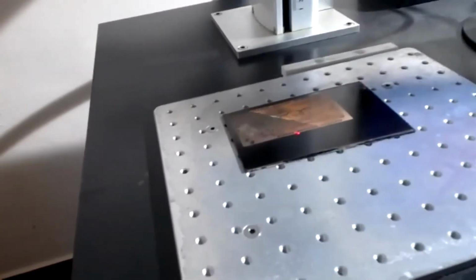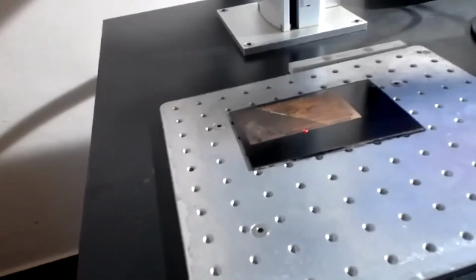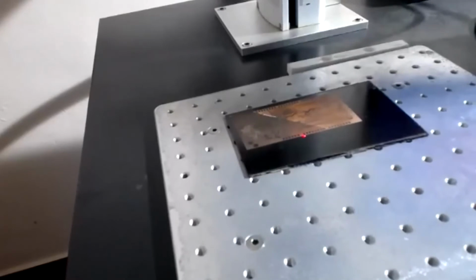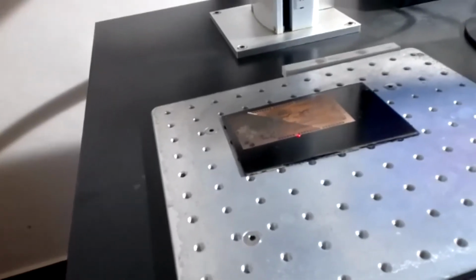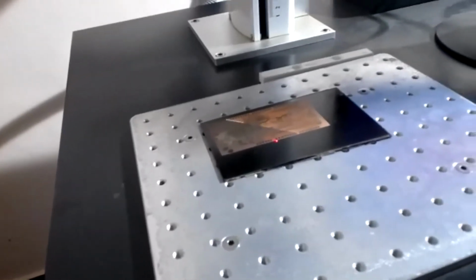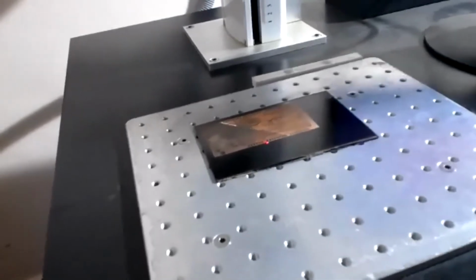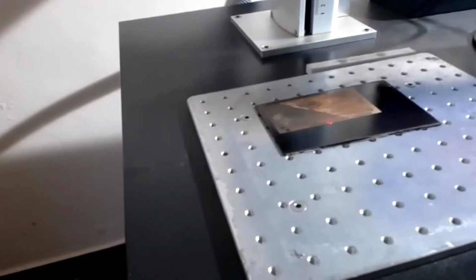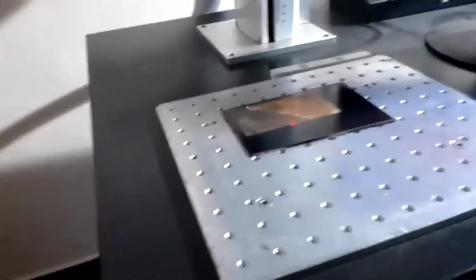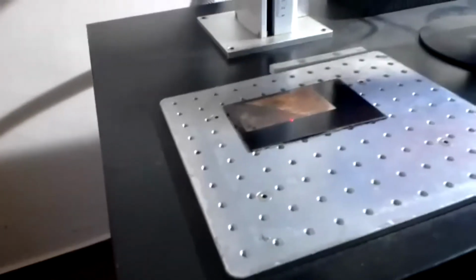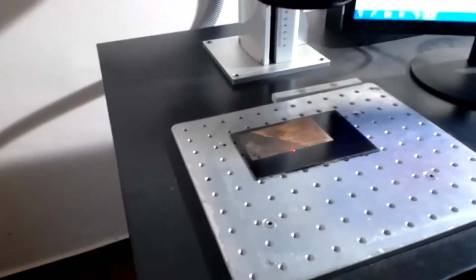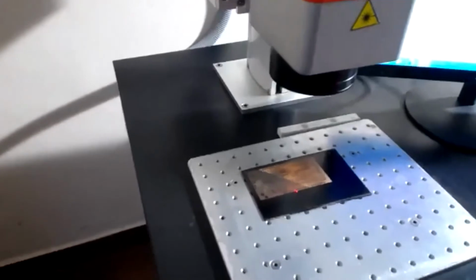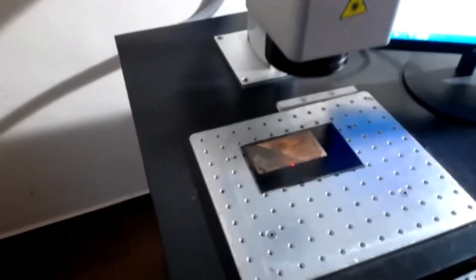One more thing is that a fume extractor needs to be connected, because these fumes are really harmful. So the backside fume extractor is the protection we need to have, and the glass needs to be lowered for protection when you are handling the laser, and power needs to be controlled. Power control is very important, because if you keep 100% power, it will cut the board itself into two pieces. Instead, it is engraved.